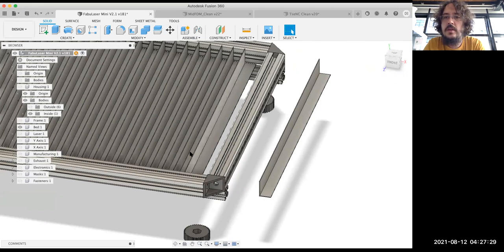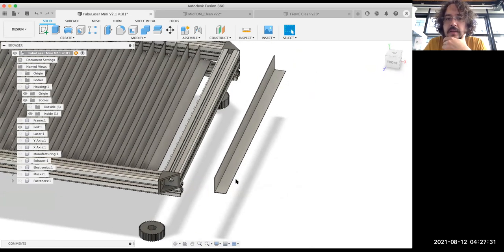And these guys have a distance between each other of 20 millimeters, roundabout. And then what happens, guys, is that this is very different from the honeycomb of a traditional laser cutter. The honeycomb is so dense, so fine, that you're going to have lots of flashbacks to the piece. With this one, you have flashbacks that are more coarse than the other one.